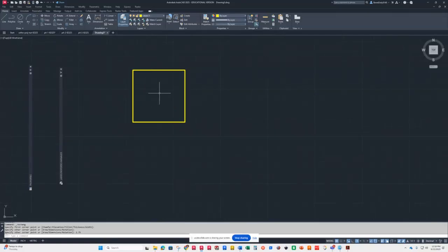Okay, so if you were to look at this from the top, it's got a 1-inch square here in the middle somehow. Now, how am I going to get a 1-inch square in the middle? Very carefully is the correct answer. So I'm going to draw me a line, and if you wanted to, you could draw the other end of the X, or you could use your mirror command. Remember that mirror command is kind of handy. Go off the middle, pull it down. There you go.